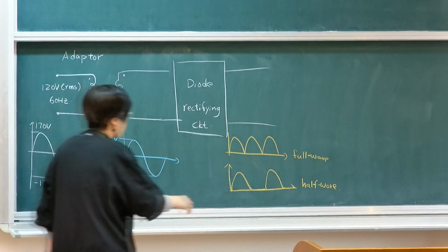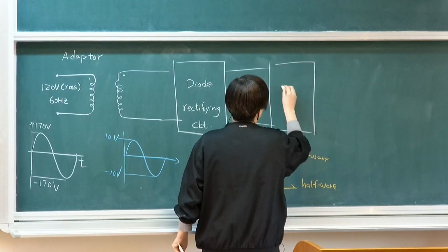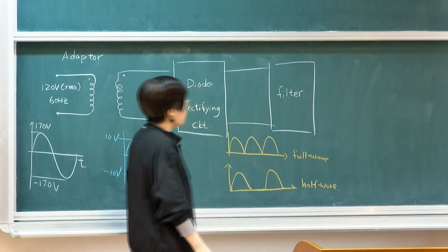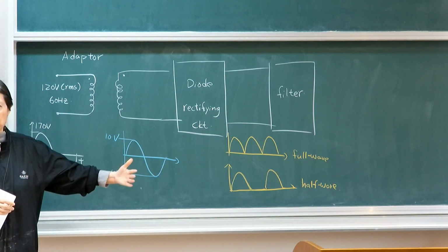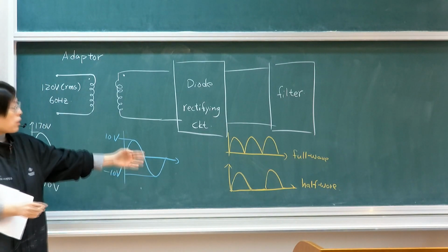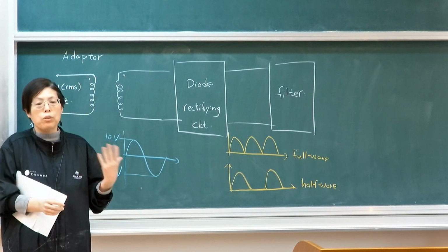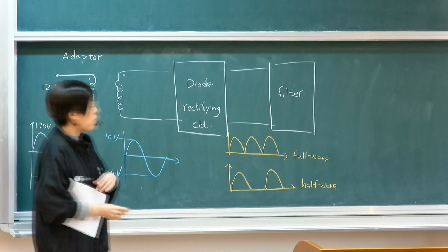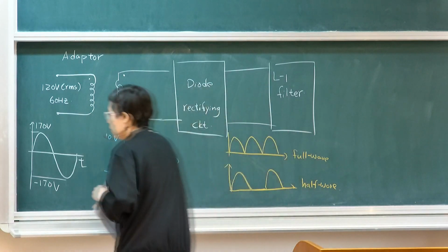This is typically through something called a filter. You just want to get rid of the high frequencies. If you look at it in the frequency domain, you do a Fourier transform of your signal. These are the higher order frequencies, so you want to take out the higher order frequency components and make it flatter. That's through a low pass filter.